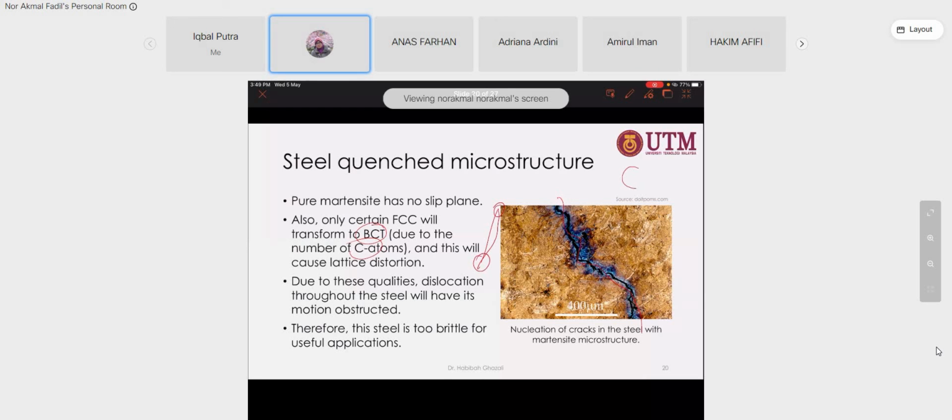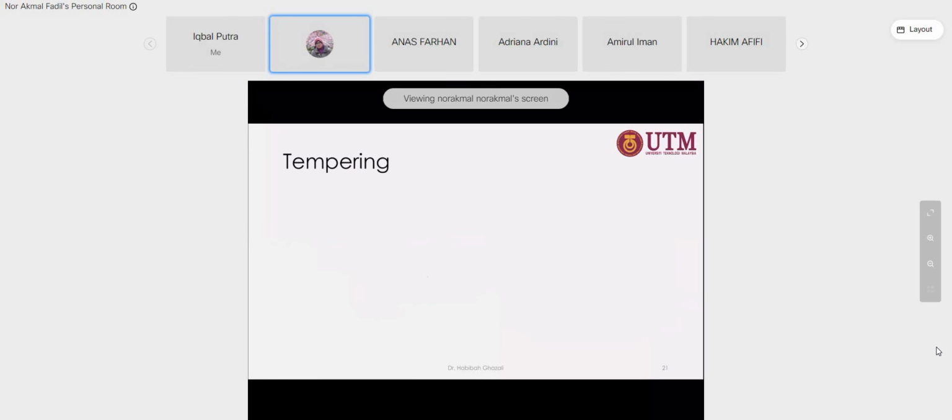Okay, if you have a nodular structure like spheroidization, remember the spheroidite process, which turns the lamellar structure of cementite into spheroidite like this, you will obtain very soft steel. This contributes to the softness of the material. But a needle-like structure like this, there is so much stress concentration. It easily causes the material to be brittle. Okay, it cracks easily.